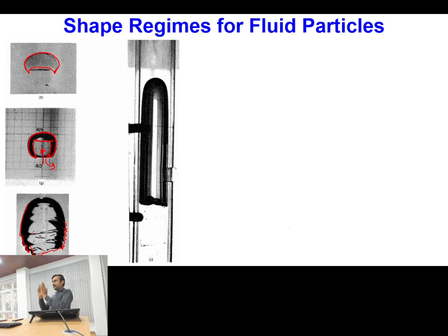A tube will have a finite sized diameter, so some wall effect will come. Because of that wall effect, if the volume of the bubble is very high, the bubble will try to attain the central portion of the tube, and it will form a longer bullet shaped bubble.